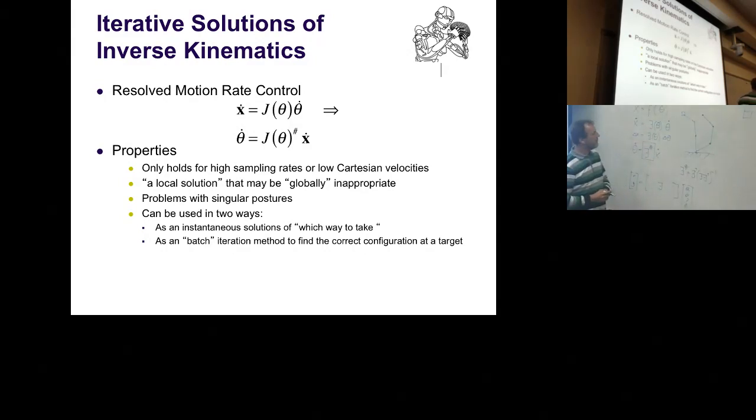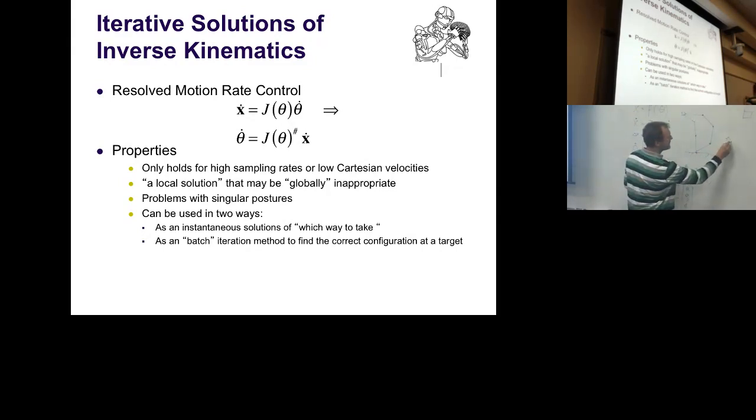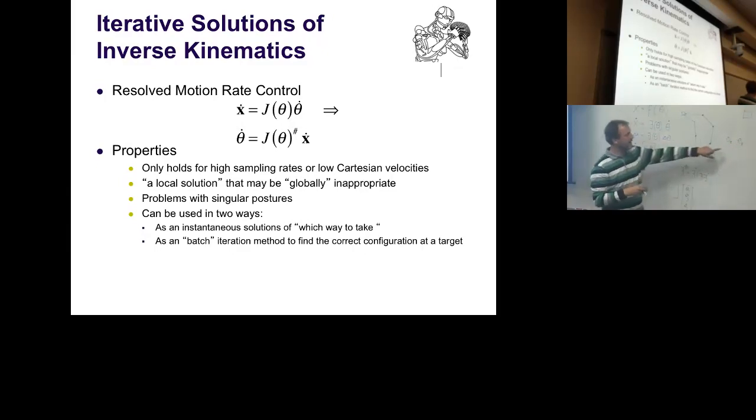Okay, make it up. Now, if I do this method where I do step by step, I will make my end effector go here. And basically, every time I compute delta x, it creates a delta theta. Delta theta I realize with some kind of PD control in joint space. Very simple at this moment. The other method, basically, I create first my theta start vector and then my theta end vector. And I just iterate in simulation until I figure out some theta end. What I can do now, I can basically say, oh no, I want to go the shortest path in joint space to go to theta end.